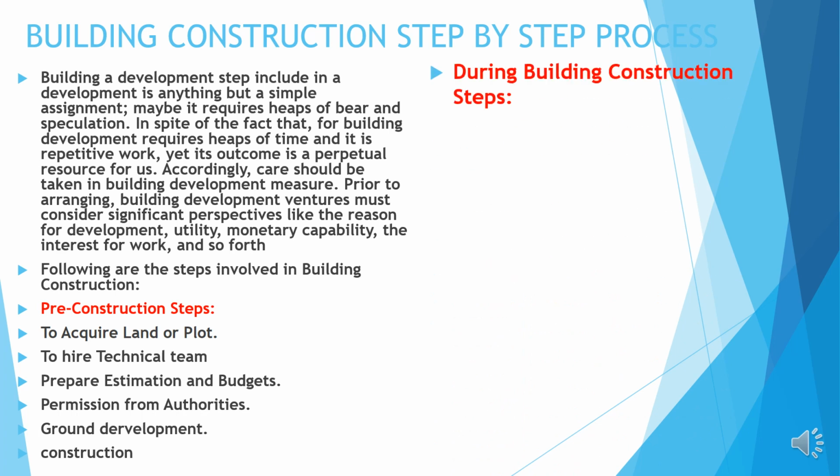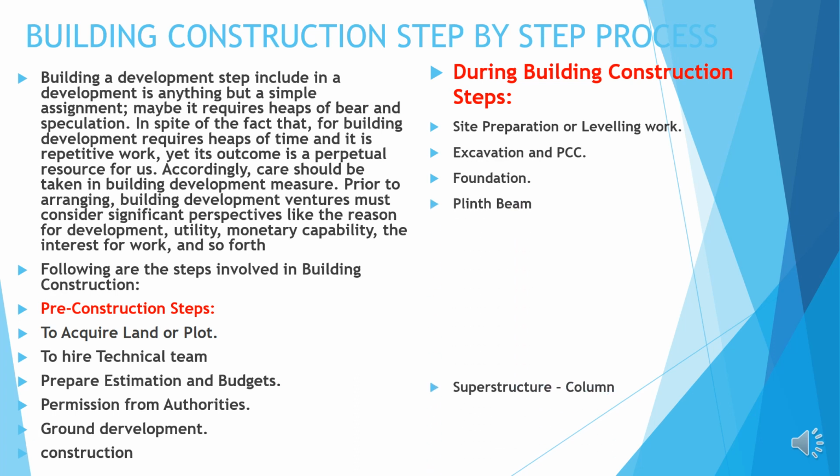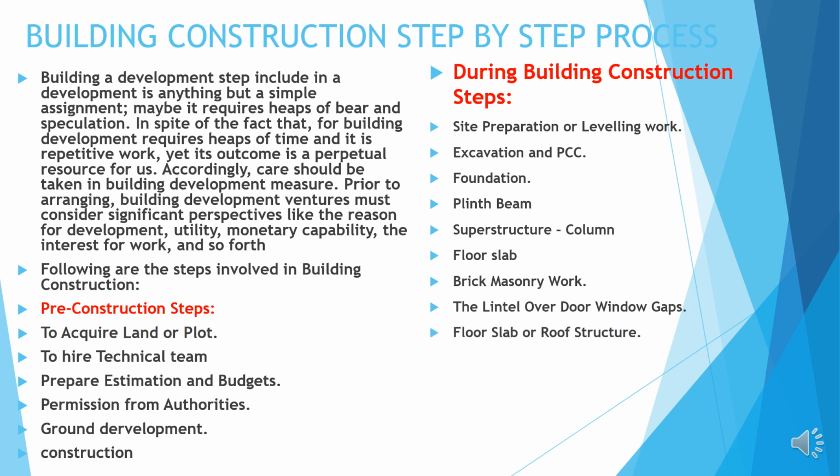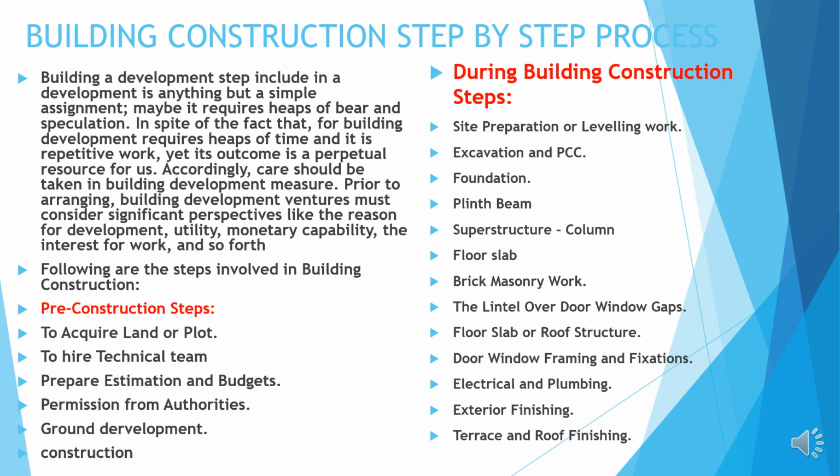During building construction steps: site preparation, leveling work, excavation and PCC, foundation, plinth beam, superstructure column, floor slab, brick masonry, lintel over doors and windows, floor slab or a roof structure, door window framing and fixations, electrical and plumbing, exterior finishing, terrace and roof finishing, internal finishes.